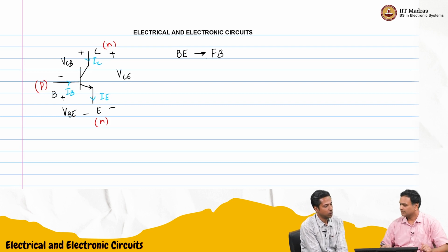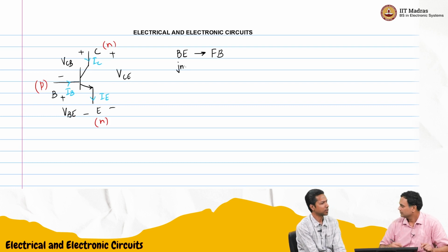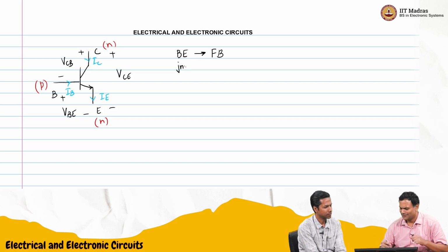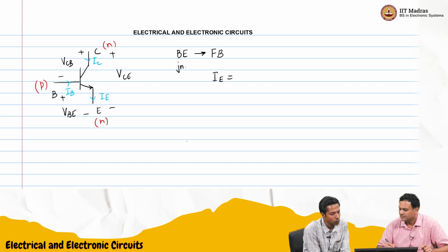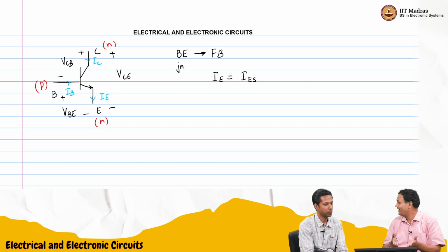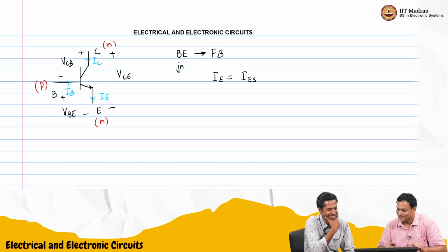So we know some expression for current in the PN junction for the diode. Can we use that? We should be able to; that should be valuable. So we'll write the emitter current now. There is some saturation current, IS, what we use. In this case, I'll call it IES, because it's the saturation current of the emitter. We have many currents here, whereas before we only had one. So we'll call it IES, e power VBE.